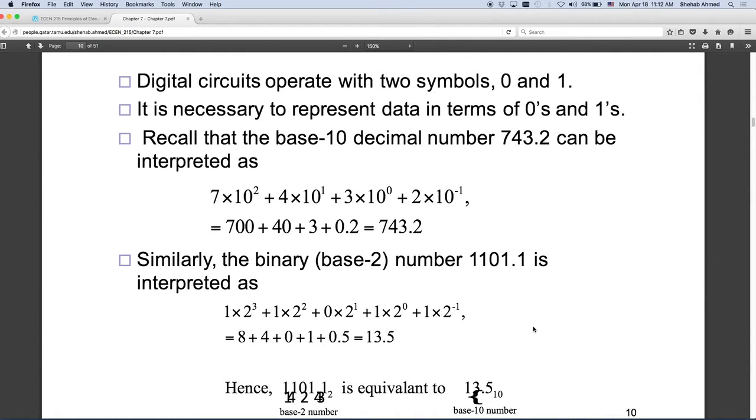So who decides? It's the engineer that decides based on what he knows about his system. You typically design a system that you know. You will design a pressure sensor. You will use a pressure sensor. Your pressure sensor is known to have a certain pressure range. So I know my pressure range. This pressure range corresponds to a certain voltage that is going to be measured.